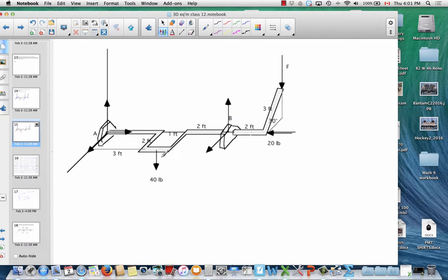Okay, so forces and moments. This is a little tricky. This moment here is going to be 3.5 feet away, so that'll be a negative I moment, and then 2 feet away for the J moment. Here, this force straight down, here's its line of action. You could see this is going to rotate around the negative J, but pushing down here, the whole structure is going to tend to rotate this way. That's a negative I moment.